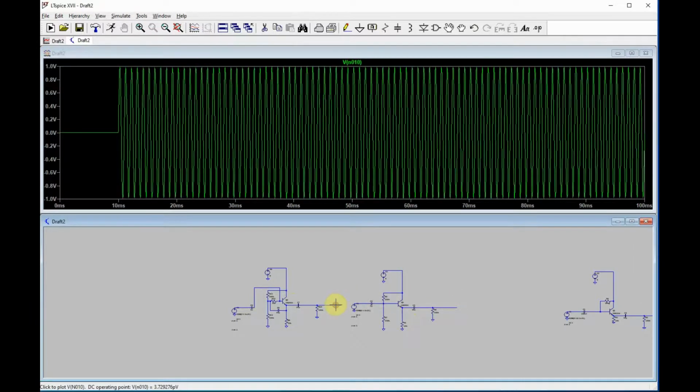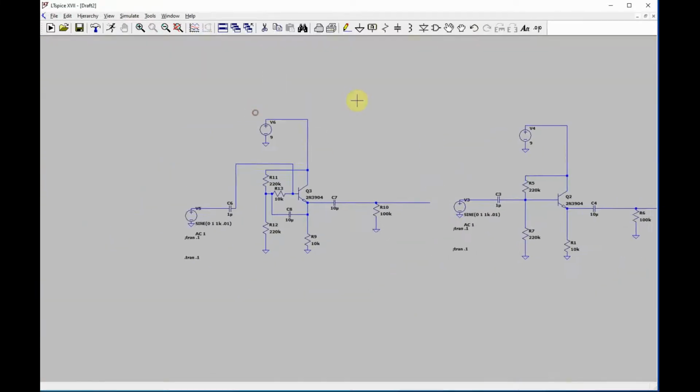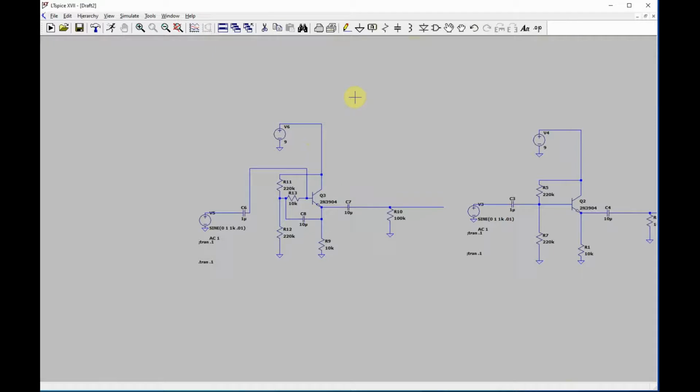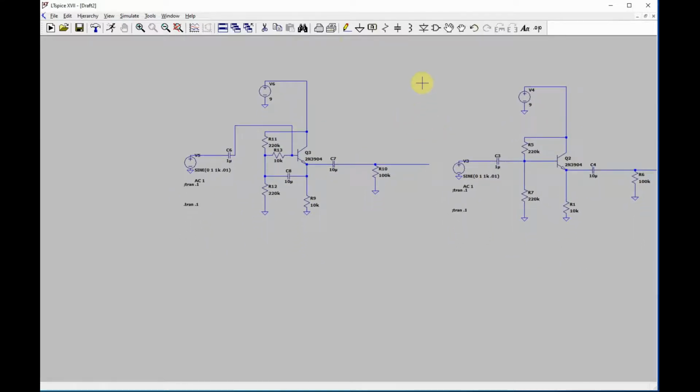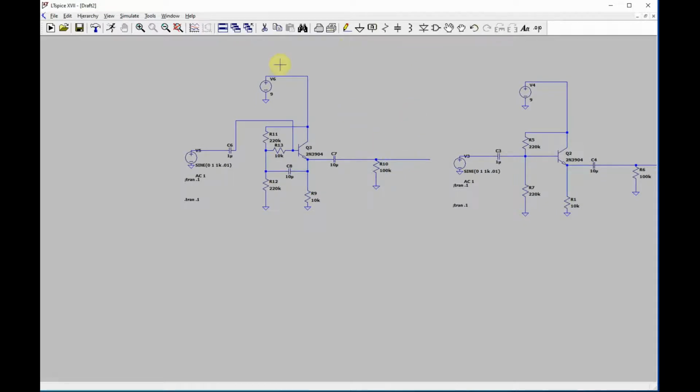It's a neat way of modifying a basic emitter follower to make it high impedance, and whenever I've seen this, it's usually written like this. Now, there's another way you can get a decent emitter follower configuration or buffer, and this one uses 2 extra parts.